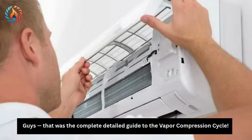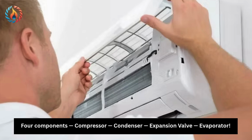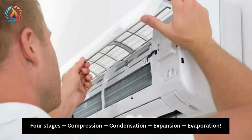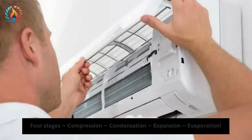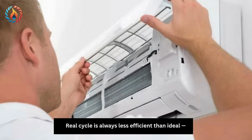That was the complete detailed guide to the vapor compression cycle. Let me quickly summarize. 4 components: compressor, condenser, expansion valve, evaporator. 4 stages: compression, condensation, expansion, evaporation. Key terms: superheat, subcooling, saturation temperature, COP. Real cycle is always less efficient than ideal.